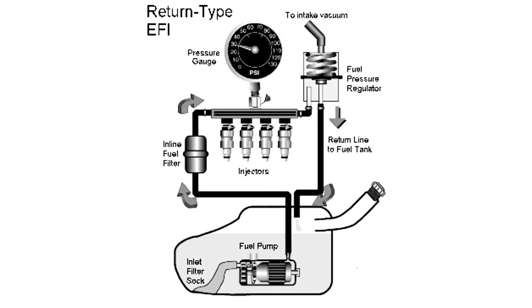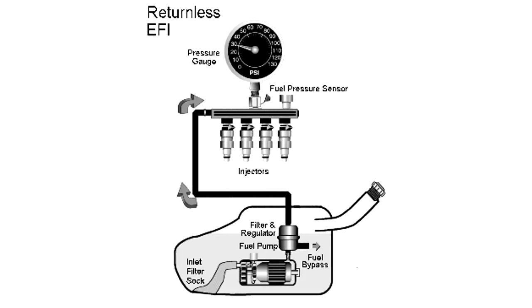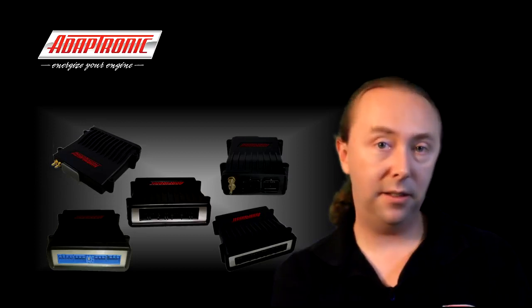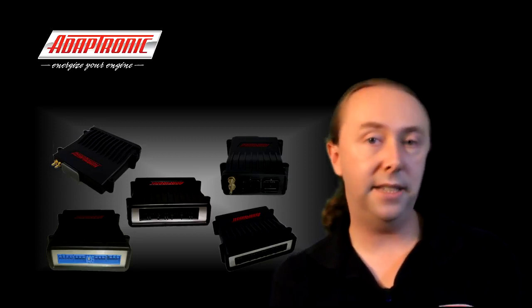Now for this there are two ways of doing it. One of them is to have a manifold referenced regulator where you'd enter a value for the differential fuel pressure, and the ECU assumes that to be a constant. The other way is if you have a fixed pressure regulator, or the fuel gauge pressure I should say, does not change with manifold pressure, and in that case the ECU subtracts the manifold gauge pressure from the fuel gauge pressure that you enter to work out the differential pressure. And again, the ECU can use this to look up the fuel flow rate and the injector dead time.